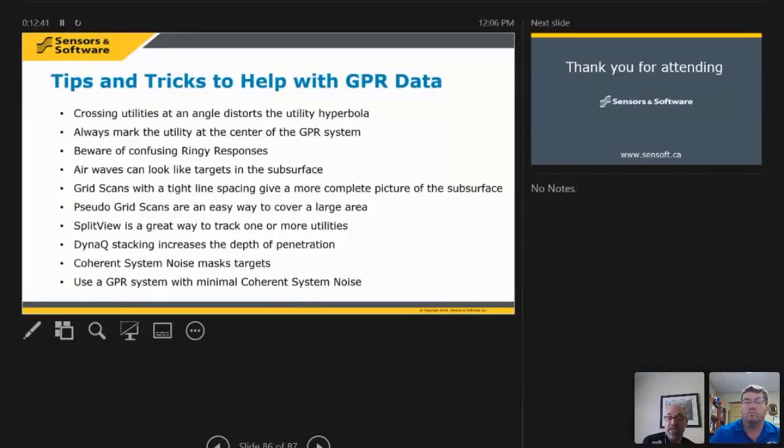It's working in gigahertz, and the reason it works is because the radio waves are exciting the water molecules and making them move. That's what heats up your food. The same sort of effect happens, and you start to see it at those frequencies in GPR. So there is a little bit of absorption of GPR signal from water.